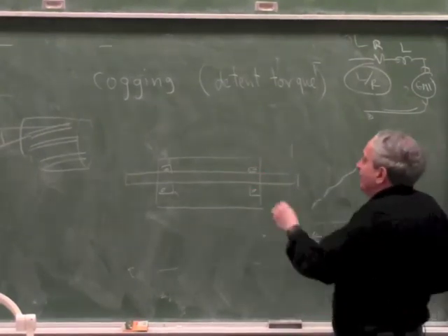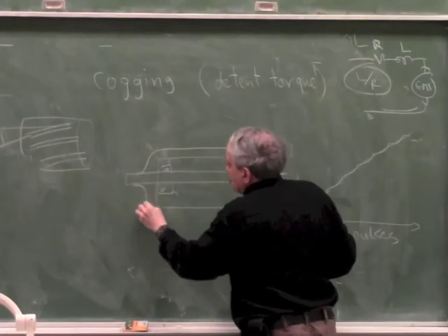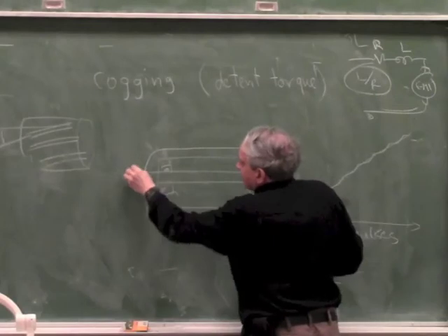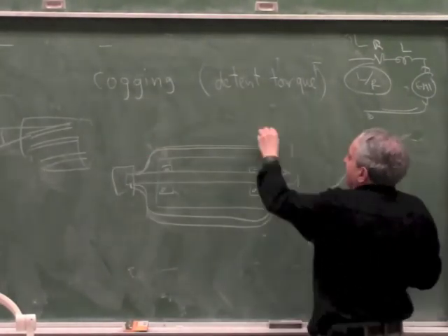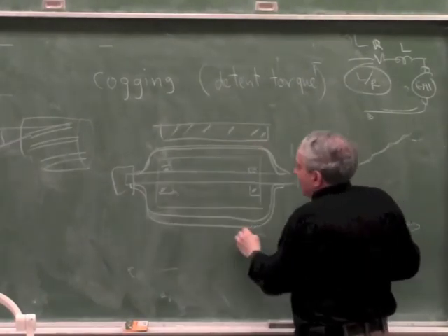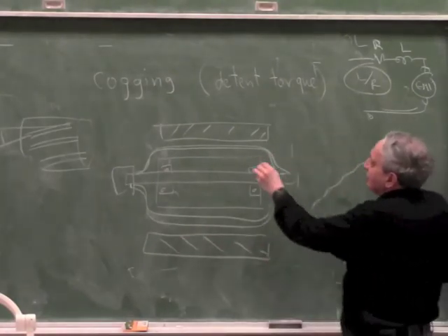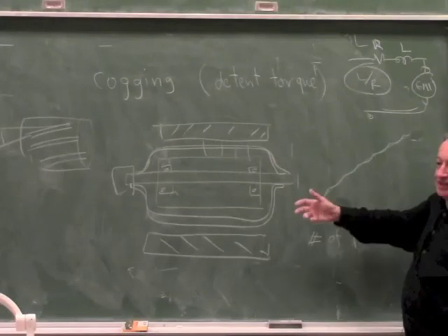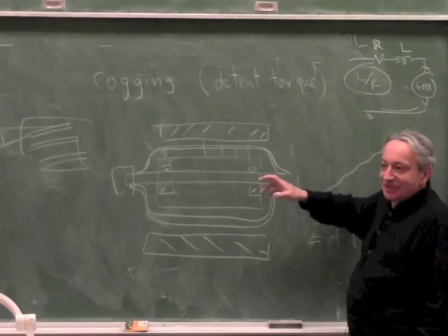Okay? And now to have the winding around it as a shell connected to the shaft. So this is a commutator and this is a winding, and the winding is a shell, and then to have the ring of steel which closes the magnetic path. So this is just a ring of steel to close the magnetic flux. So what happens when this motor accelerates, the magnet is free spinning on the shaft. It doesn't have to accelerate.